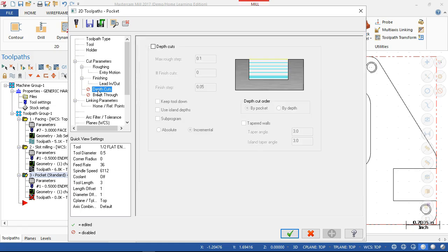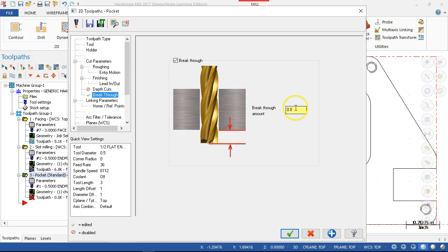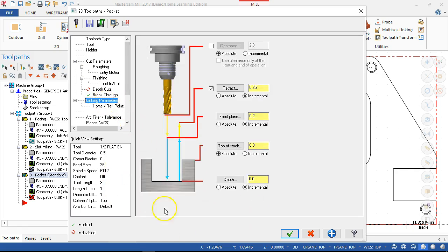Depth cuts. We said we weren't going to do depth cuts. Maybe I'll bring the pocket through 5 thousandths. The check for this is if I go negative, it gives me the value 0 to whatever; you can't put it in negative. It's going in that direction, continuing in that direction, so it's a positive value. And then same things, we're going to go back to absolutes.